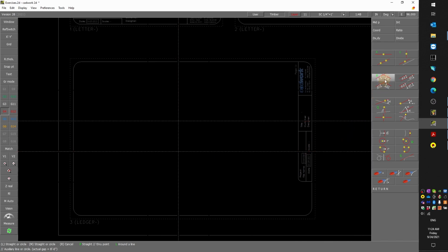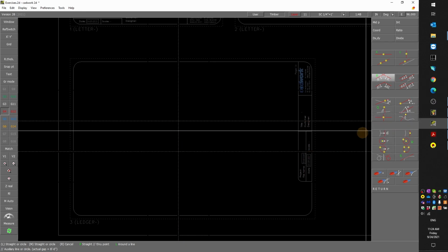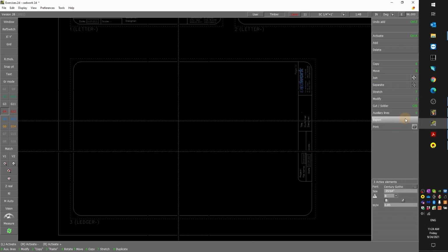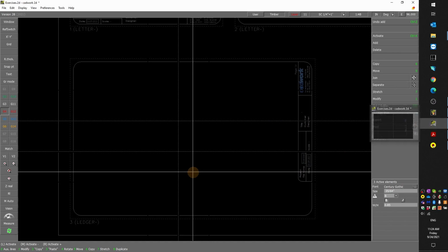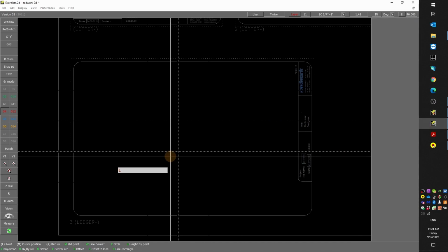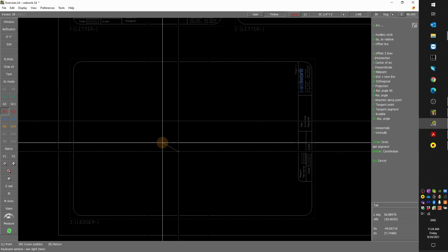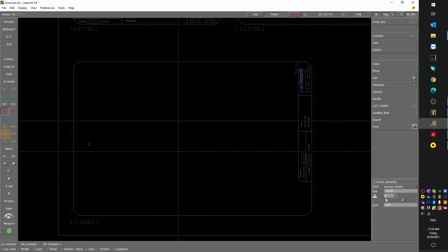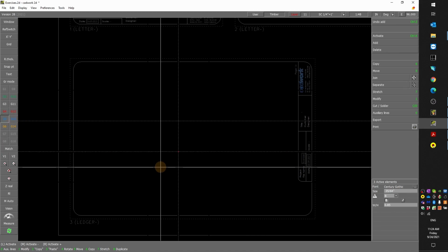Then I should be actually able to do this without auxiliary lines. So let me show you how. So I press L. We're gonna add a surface in G4. So let's just switch back to G5. I'm gonna create blue lines.